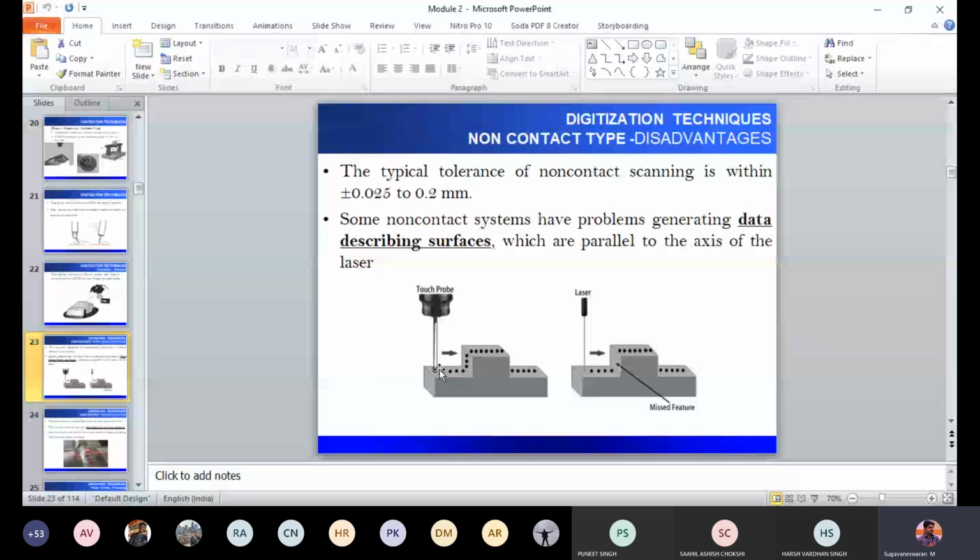This is the contact method. In the non-contact method, you need not touch, because when you touch a component you have some issues. For example, if the component is very fragile in nature, when you touch it, the component tends to deform. So instead of 2, 2, because of the deformation in the part, you may be getting 1.99, 1.99. So that will not give an exact value when you touch a component, because of the deformation associated with the part, as well as the deformation because this rod will also tend to bend. If you apply a load, definitely it will have a minor buckling.